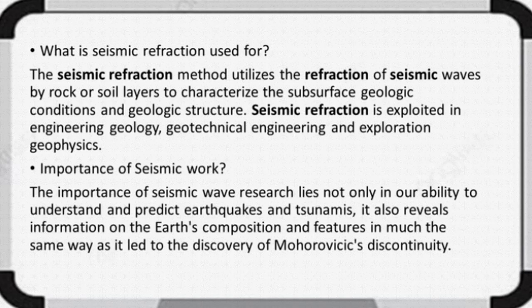Number 8: why is the seismic method important? The seismic method is by far the most important geophysical technique in terms of expenditures and numbers of geophysicists involved. Its predominance is due to high accuracy, high resolution, and great penetration. The widespread use of seismic methods is principally in exploring for petroleum. Seismic methods are also important in groundwater searches and in civil engineering, especially to measure the depth to bedrock in connection with the construction of large buildings, dams, highways, and harbor services.